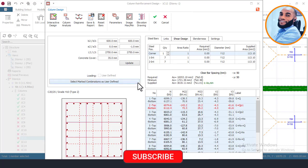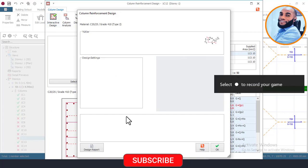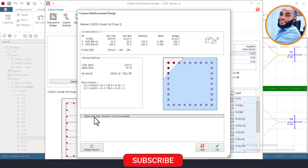On this place, the first thing we'll do is check the reason why the column is failing. I said that in part 15 earlier. So I'll click on this place here that says interactive design, and once I do that, there will be a warning around this place to show the reason why the column is failing. Okay, you can now see that it says that the steel ratio limit is exceeded.